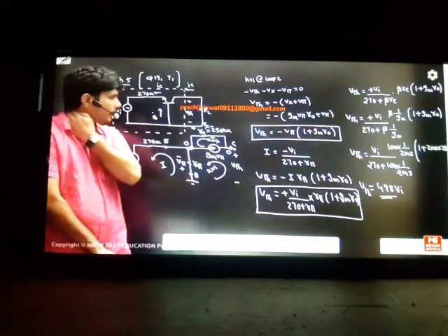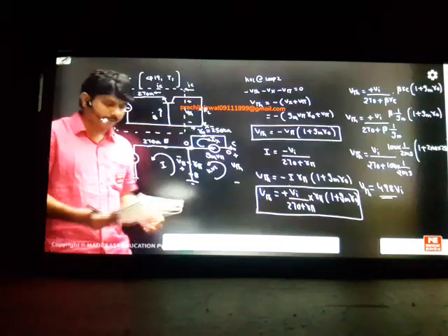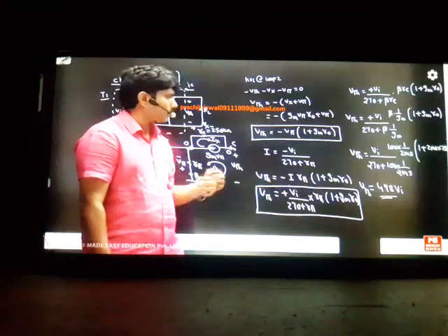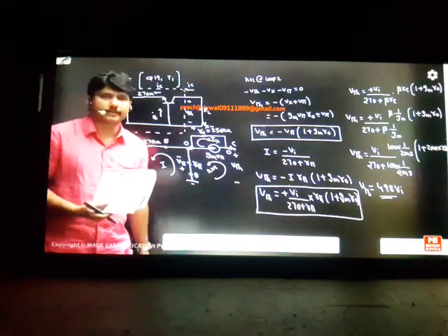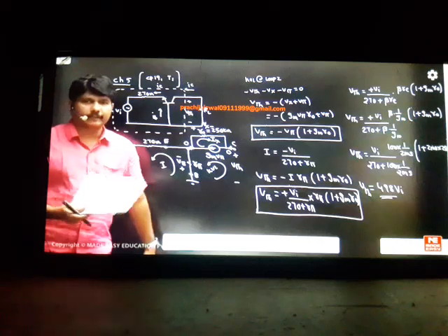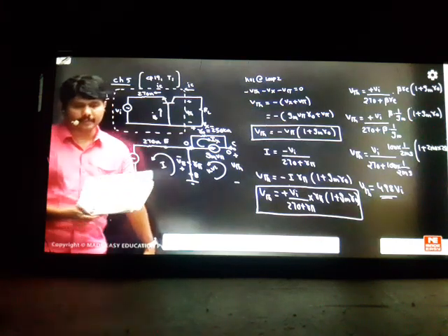Okay? So this is the way we can solve this type of Thevenin problems. They're looking very interesting. That's why EC students, please try to understand this question. At GATE level, they may ask you this type of questions. Just write the equivalent models properly, and by finding the KVL relations you can find the answers. You'll get the answers very nicely.